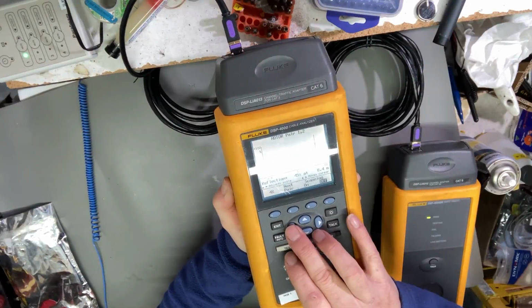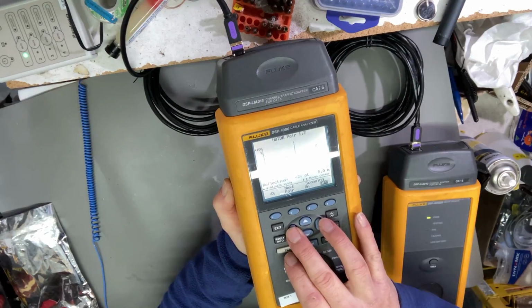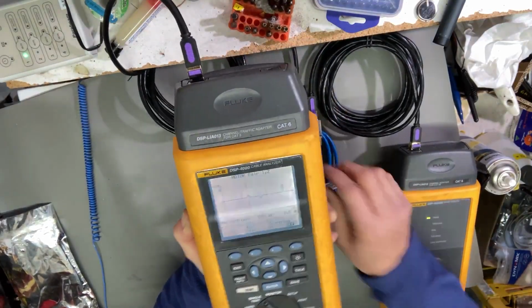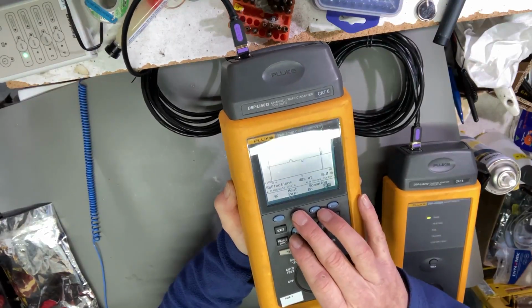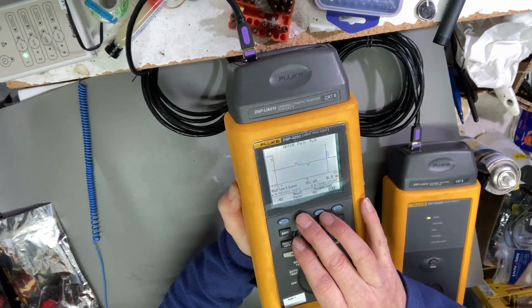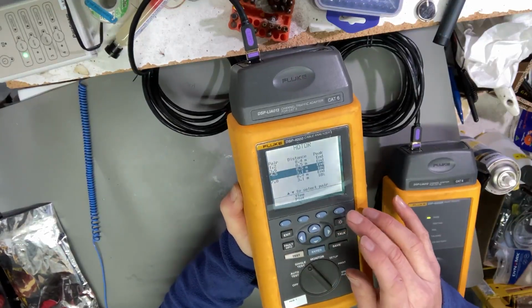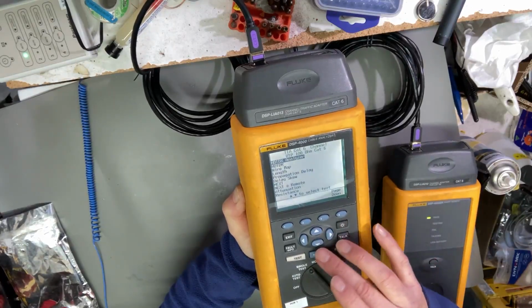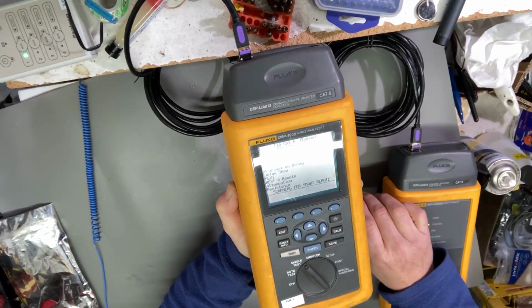But again, we can see these places where the impedance has changed in the cable, the two connectors there. Next pair. Okay, so I'm just going through the different pairs now. That doesn't actually look too bad using that test, but clearly it failed, and the previous single test, that analyzer test, was really enlightening. I'm just going to do that one again, because I didn't go through the different pairs, I think.